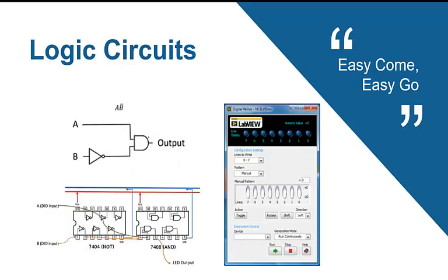So to make this circuit in hardware, for example, we have here A B dash, because we have B dash, and A with B dash connected to an AND gate will be A and B dash. To make this, it means that I have to use a NOT gate, and also I have to use an AND gate. Okay, so first for the NOT gate I need to invert B, so I will connect B here on 1 and will get B dash from the second leg.